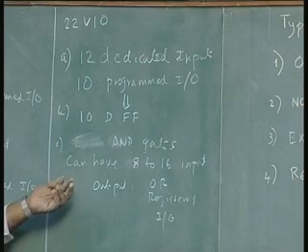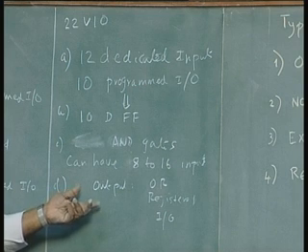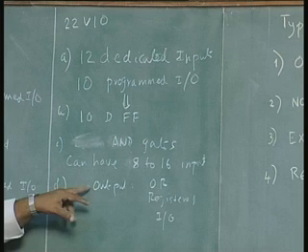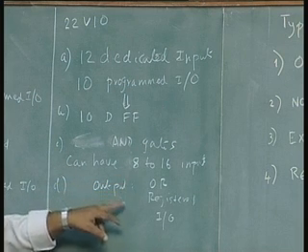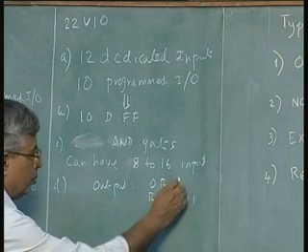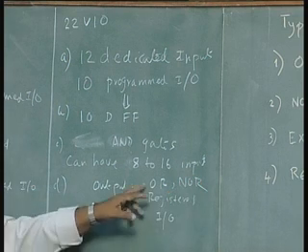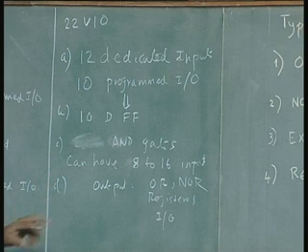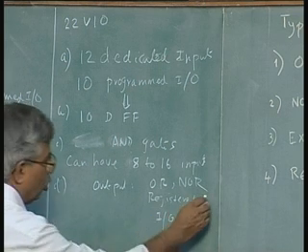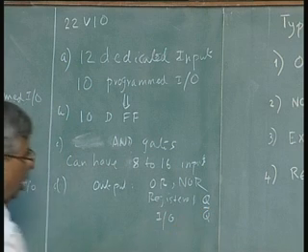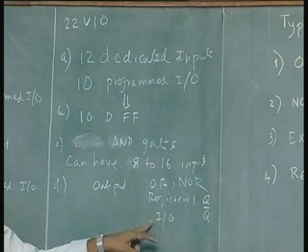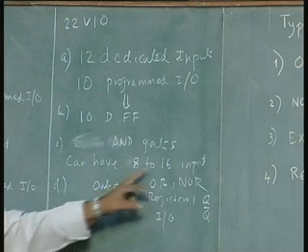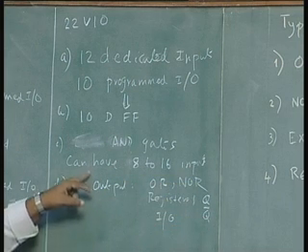But what I want to say quickly is these outputs are very nicely done. There is a little block at each output. This block decides whether the output is a combinational output, which can be OR or NOR. I can have an OR or a NOR output, or I can have a registered output. There is a multiplexer between OR output, NOR output, registered output. Again, register can be either Q or Q bar, or I do not want any of these. I can go for input option. All of these things are possible. So this is an extra nice logic at the output of each of the pins.